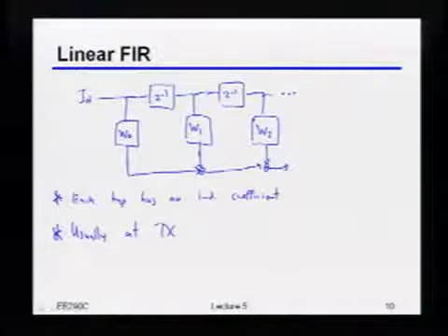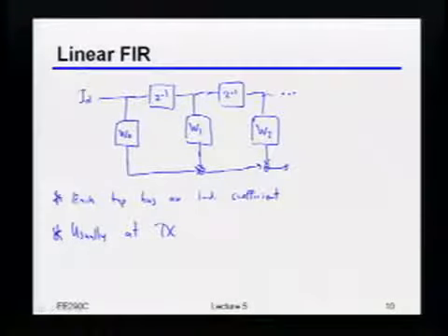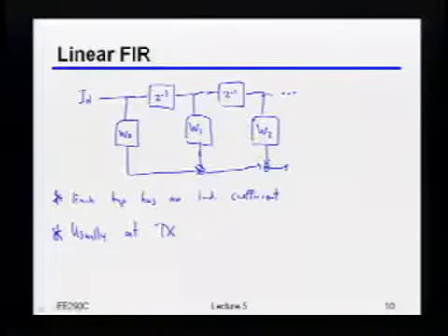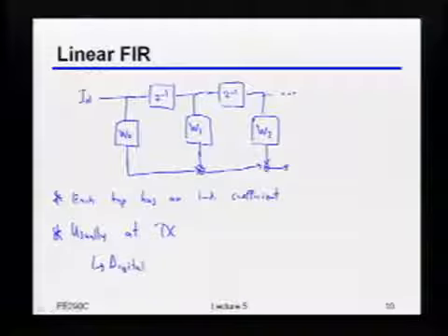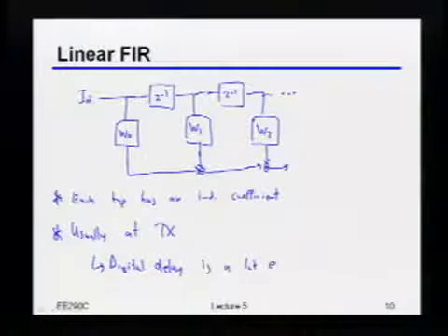Anybody know why it is that you usually do this at the transmitter, and not at the receiver? Yeah. Also, you don't need like an ADC. It's probably easier to. Okay, so you said no ADC. That is true, although that's probably not the fundamental reason. You can easily delay it by using flops. Ah, there we go. It's actually the delay that's the biggest trick. It just turns out digital delay is a lot easier than analog.